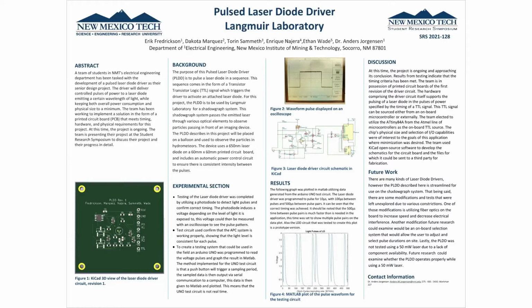So part of the project was developing a simpler, more lightweight, cheap version of a cruder O-scope, so that when this is being set up in the field, the team will be able to confirm the laser is pulsing as expected. This was done using a photodiode and a transistor to essentially create a switch that will allow 5 volts to pass through when the light pulses.